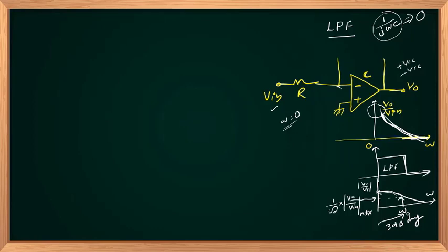Right? So let us see how it functions as an integrator circuit, or why it is called an integrator circuit. It's quite simple. The current flowing through the resistance in this direction, I, will be equal to V in minus 0 by R. I'm assuming feedback exists, and V plus equal to V minus. And the same current flows through the capacitor. Its voltage will be plus minus Vc.